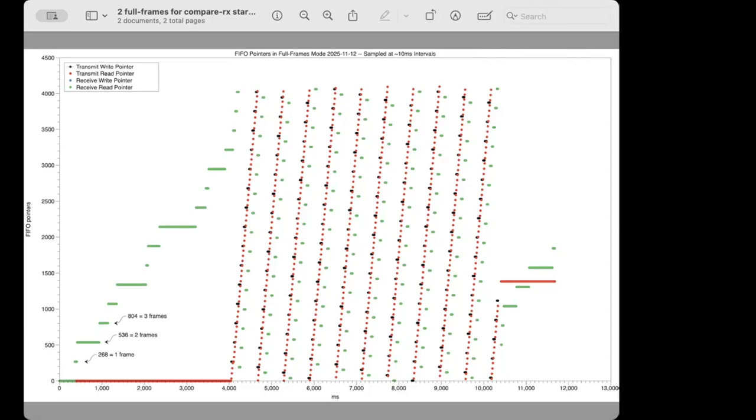And then the green, during the portion of the test where I'm transmitting, it's also clocking along. You can see there's a couple of frames of latency, but it is putting out a frame of received data. This is on the RF loopback. It's receiving a frame every 40 milliseconds, just like it's supposed to during that transmission.